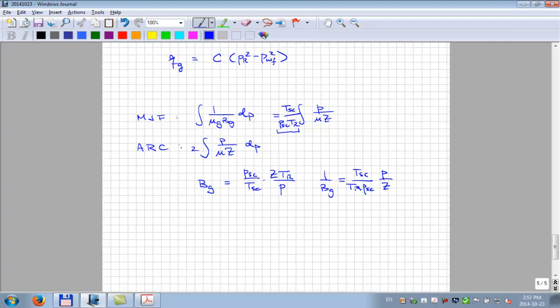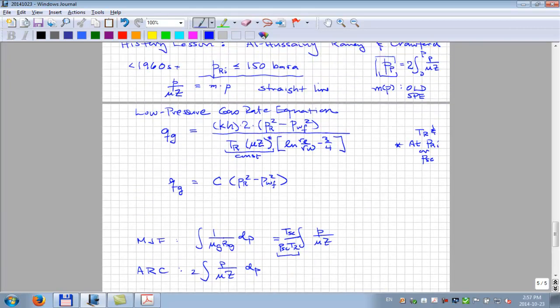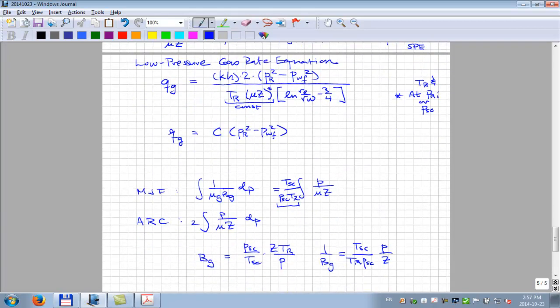Excuse me, sir. Would you please explain again why they use 2 in this equation? Well, you see, the way I've written the equations now, they're for consistent units. Cubic meters per second, permeability given in meters squared. I mean, it's completely consistent units. We don't use those kind of units. We use cubic meters per day, and we use millidarcy, and we end up with a numerical constant that does all these translation of these units, okay?